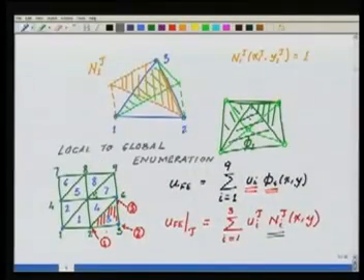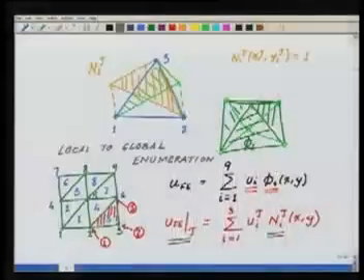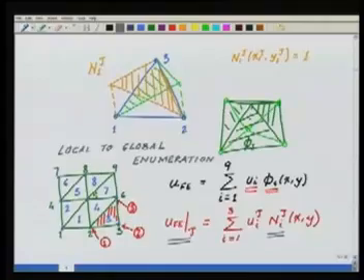Similarly, the n1 tau for this element is equivalent to the phi 2 in this element, n2 tau is equivalent to the phi 3 in this element, n3 tau is equivalent to the phi 6 in this element. Okay. So we know this one-to-one correspondence between the global solution and what we are doing locally. Once I have the representation of the finite element solution in the element, I can go and do the next step, that is I can do my element calculations.